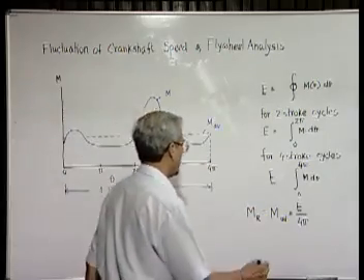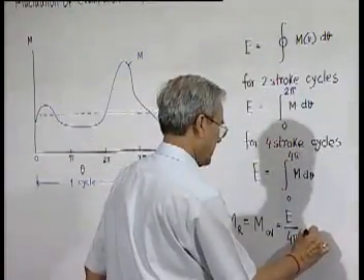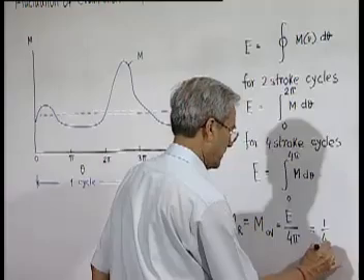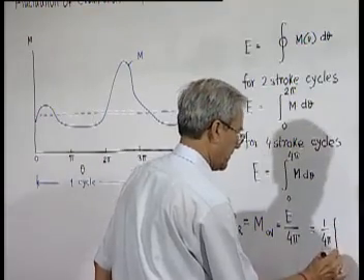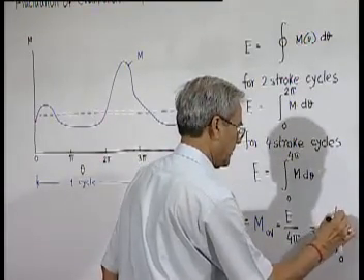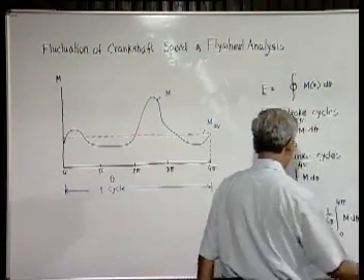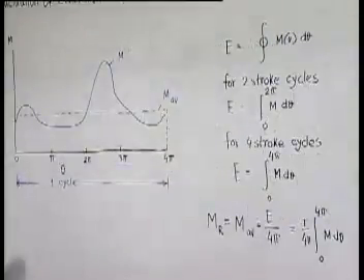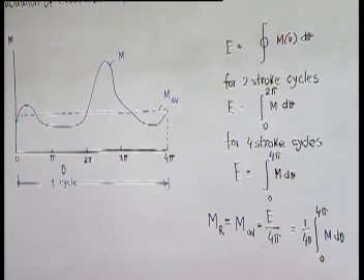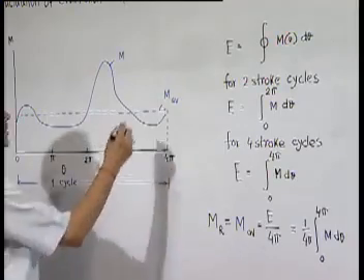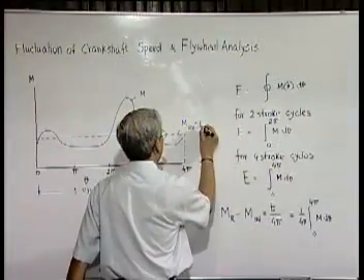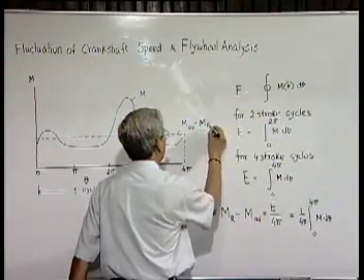That means we can write it like this. So once we know the turning moment diagram, it is possible for us to find out the average moment, which happens to be the load or the resisting moment.